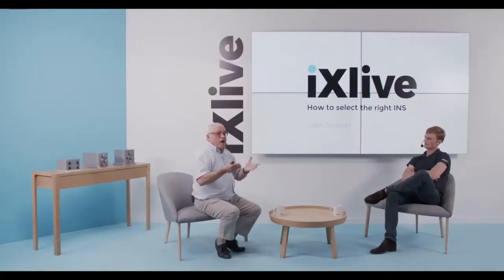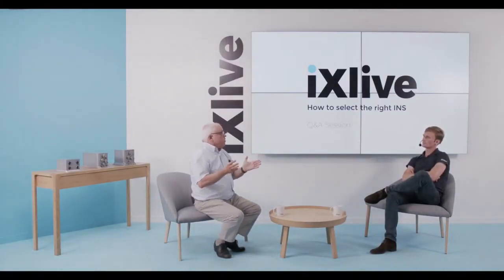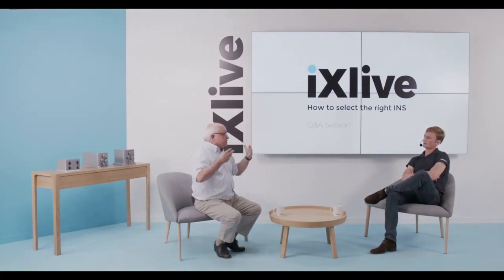And so we project these three components on the horizontal plane, and we compute the direction of this projection on the horizontal plane with respect to true north. Okay, well, and this is the way we do it in INS. But as I said previously, you need to have measurement of the rotation rates with a very good accuracy, at least better than 0.1 degree per hour.